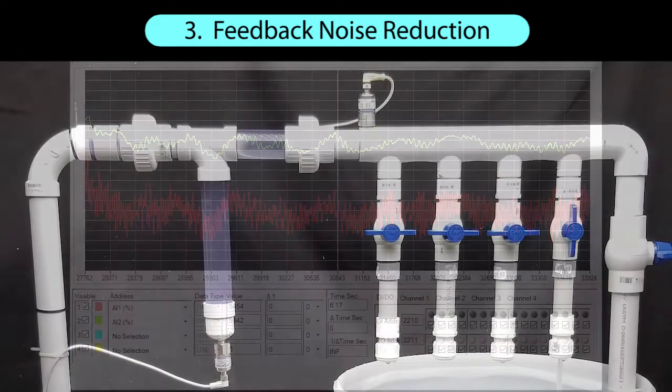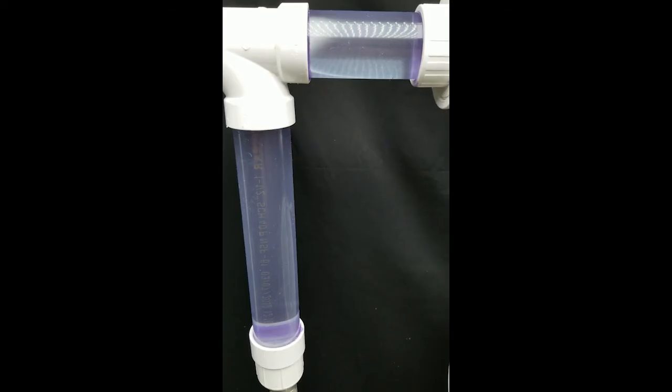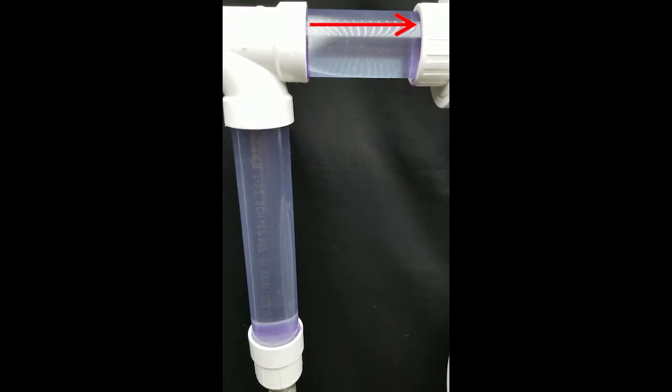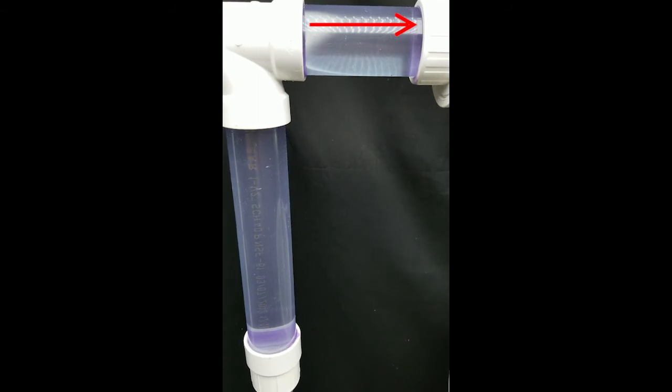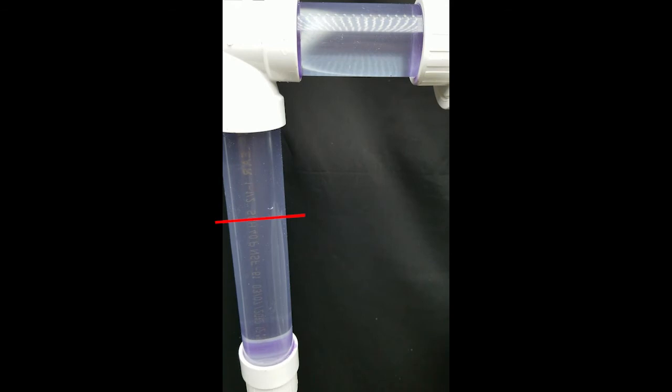The rule of thumb I like to use is to place a sensor at least 5 pipe diameters away from any turbulence generating junction. So if this is 1 pipe diameter, then we should place the sensor somewhere around here. But just for fun, I used this clear PVC so we could actually see what the water flow is doing. Here you can see the PVC flecks I put in the water screaming by, but down here, they're just gently floating around. So really, we probably could have put the sensor someplace up here and been fine.